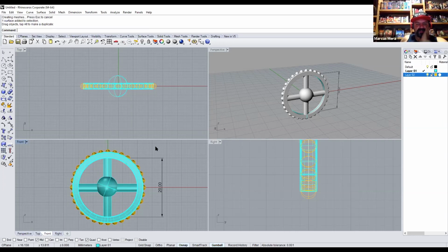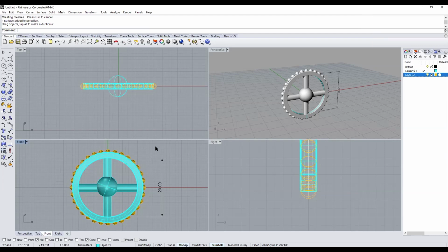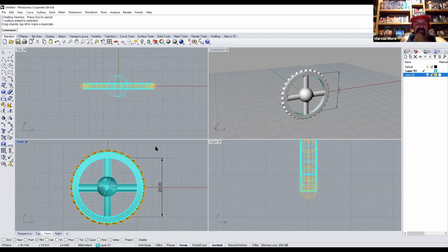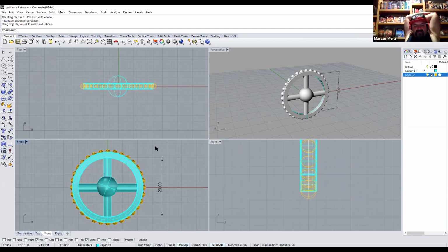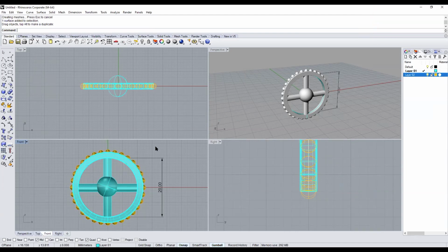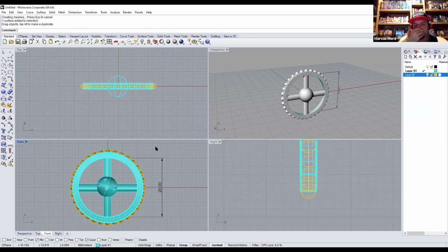And I want you to fillet the edge, 0.2 millimeters on the top and 0.1 millimeters on the inside. Fillet edge, 0.2 millimeters on top. And you said 0.1 on the interior? 0.1 on the interior. Yeah, 0.2 on the top. Okay. 0.1 on the inside. All four corners have to be filleted.